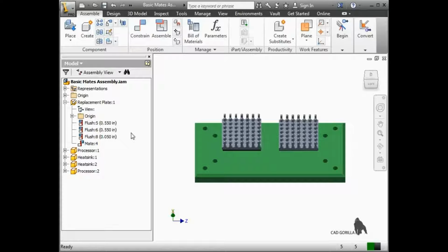In this example, all of the constraints were kept intact, even though the parts ended up in the wrong position. I was able to quickly make changes to update constraints on the offsets. If the constraints had failed, there are a couple of options. You can delete the constraints and create new ones, or you can edit them to select new geometry. Whether you repair constraints or create new ones depends on the type of errors and how many there are. Each assembly is different, and you can end up deleting some constraints, repairing the rest, and then creating new ones to finish the task.